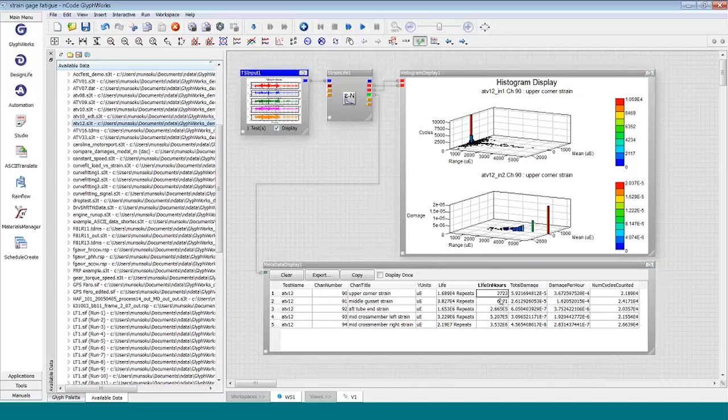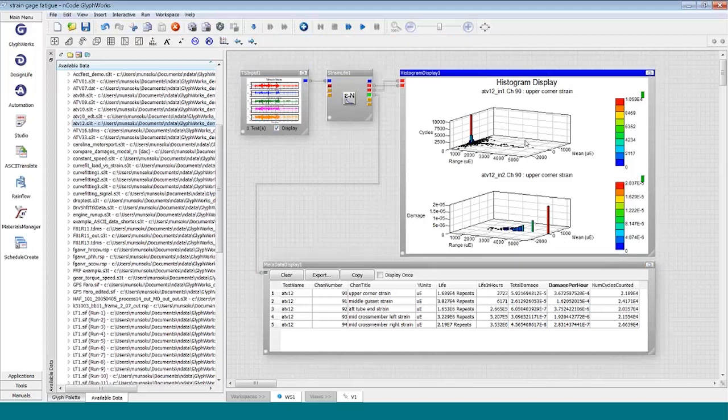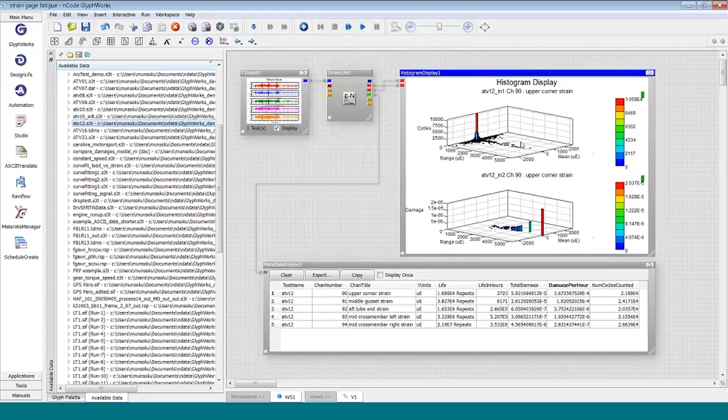This plot here shows us the rainflow cycle count, how many cycles of what size, and down below how much damage was caused by each of those cycles. If we were to total up the damage from all these bins here, we'd get back to this, because after all, that's what Miner's rule says. Linear damage accumulation. As more cycles occur, more fatigue damage accumulates until the possibility of fatigue failure exists as well. So this is very briefly how we might approach the question of strain gauge-based fatigue.